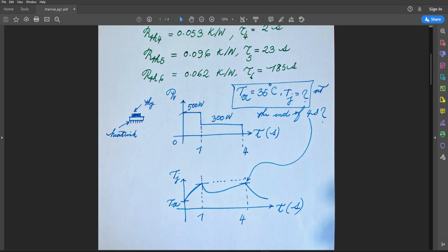If we have sinusoidal or half sinusoidal load forms or power forms, maybe from the machine theory, you know, there are different characteristics of loading. S1 is for continuous loading, S2 short time loading, S3, S4. We will see in future tutorials how to calculate the temperatures for these different types of loading.